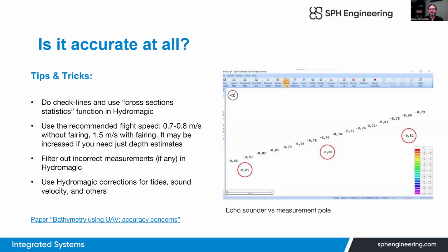To exclude the factor of instability of the flying platform, we analyze the data from the internal tilt sensors of the drone. We log the angles of the sensor with every measurement, and we may also automatically reject measurements when the sensor was far from vertical orientation.